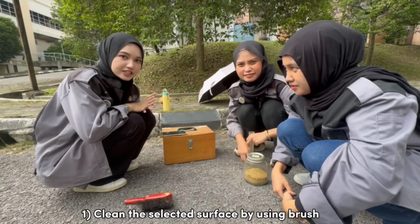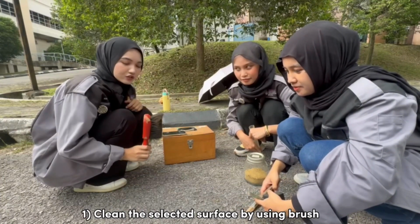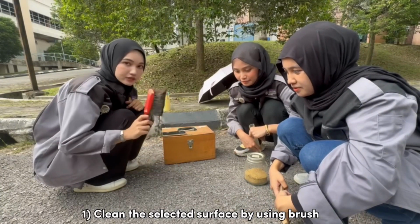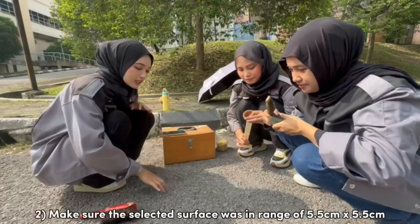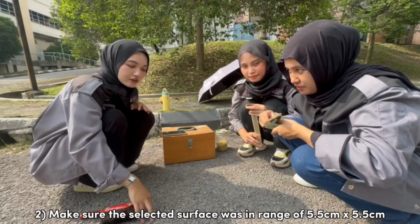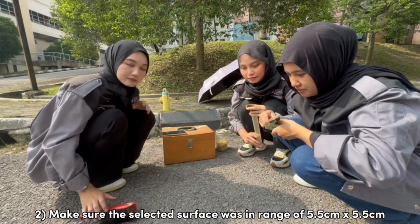Okay, for sand patch test, after we have prepared the apparatus, first we need to clean the surface of the road by using a brush. Ensure the road has a range of 5.5 cm width and 5.5 cm length.